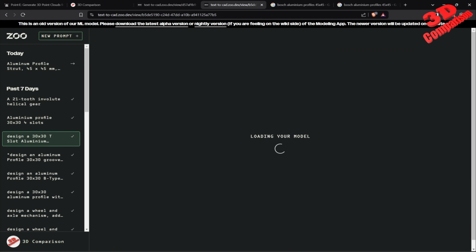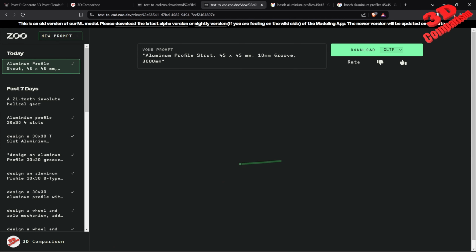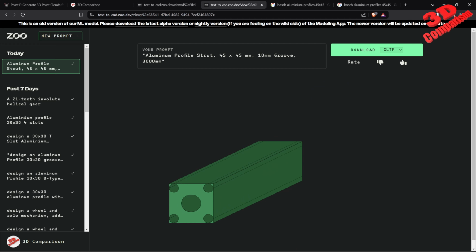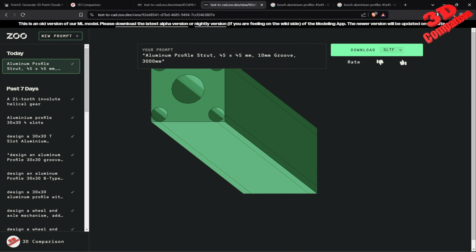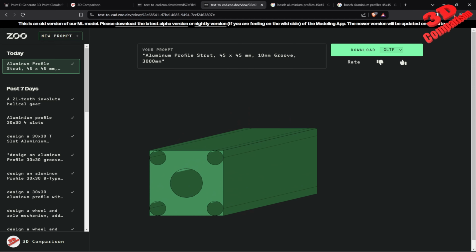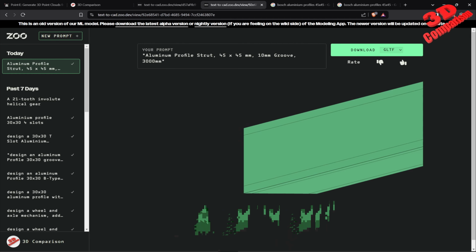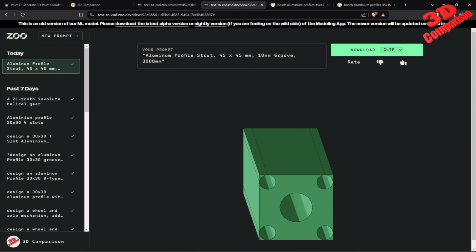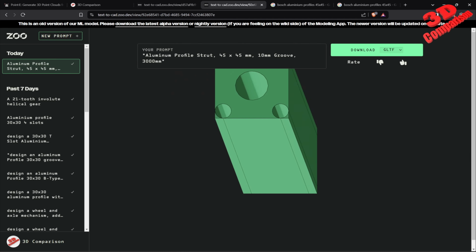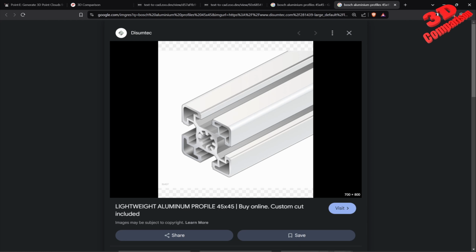And let's see the one that I generated now. If I'm gonna zoom in onto that profile, we're gonna see that it will look like this. So again, it's not a good design, especially over here onto the sides. We're gonna see that the cutout will be so close to the edge that this corner part will just be unusable, and you cannot manufacture that.